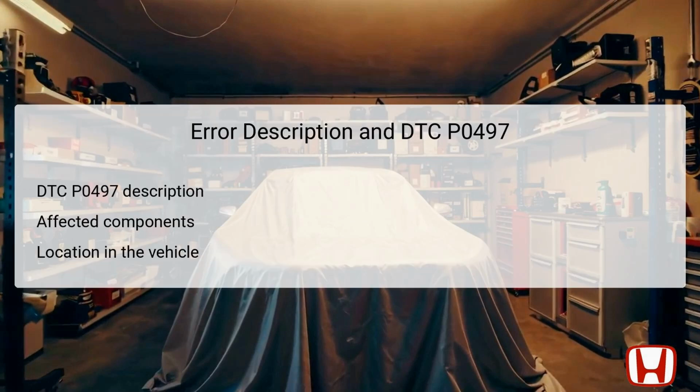The DTC P0497 specifically indicates that the EVAP system is experiencing low purge flow detected, signifying potential issues within the evaporative emissions system. The primary components affected include the EVAP canister purge valve, the fuel tank pressure FTP sensor, and the accompanying lines that connect these elements.